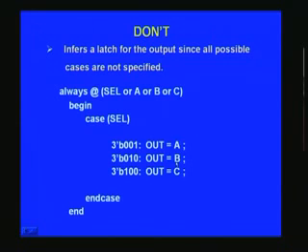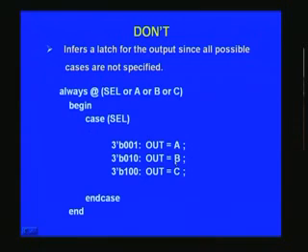So the previous value was this. Now in the present case, let us say one illegal thing has come. So it is not in any of these. It looks here and finds no match. So what can it infer? It will be confused. It doesn't know what to do. So what it will do is merely latch whatever was the previous signal as such. In this case, it came from B, so it continues to be in that state. And this may be detrimental for your circuit design as such.